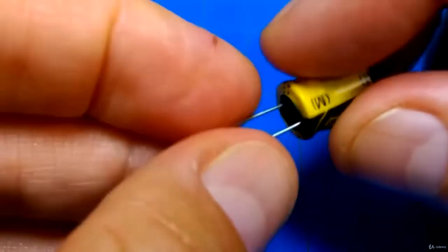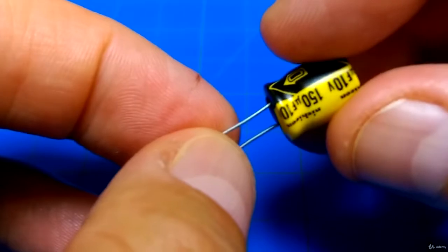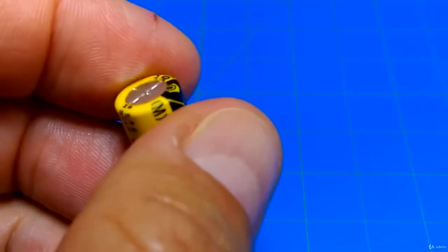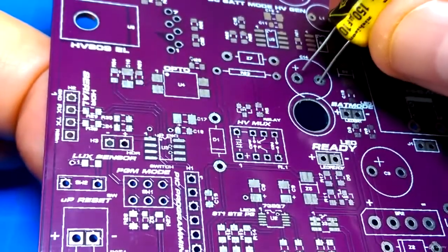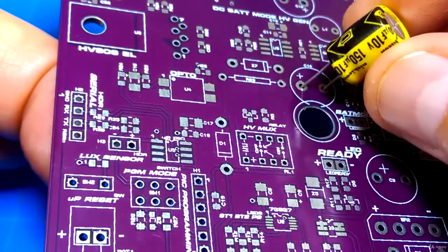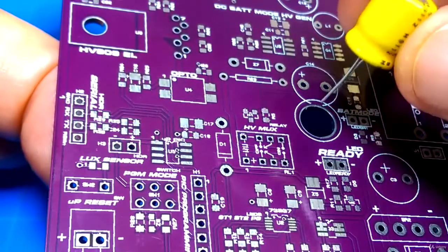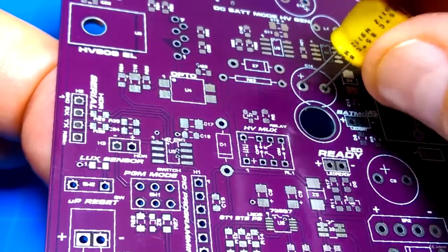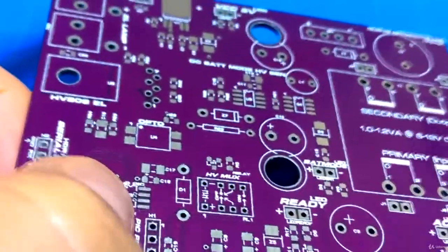All right, now this is called a radial capacitor, and the reason why it's radial is because the leads are out here radially. All right, and so if we have a circuit board like this one, put this one in here, and we can see where this guy could go in a place like that, and I just put it in wrong, right? So a capacitor goes there, but you can see there's a plus there. I actually put a plus to remind myself that's the plus side, so the other side's minus. So when I actually manufacture or assemble this, I would put that in there like that, and then I would solder it together like that. Okay, so that's radial.